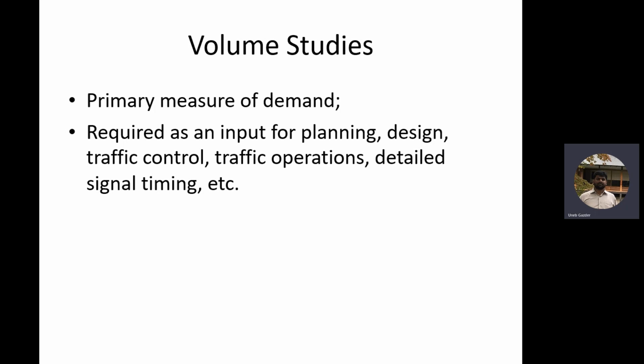Okay, the volume which you count, like I said, volume is affected by demand. The volume studies provide you an indication about the demand because they are directly proportional, right? So if you are doing any planning for the future, designing a highway, a new traffic control system, a new signal, a new roundabout, doing something with traffic operations, changing the speed limit, or changing the number of lanes, in all these cases you need the volume studies.